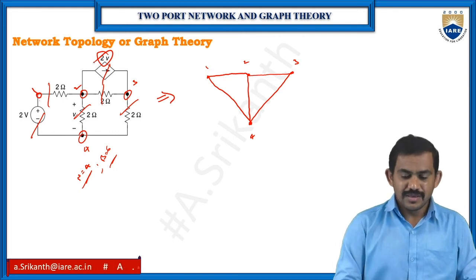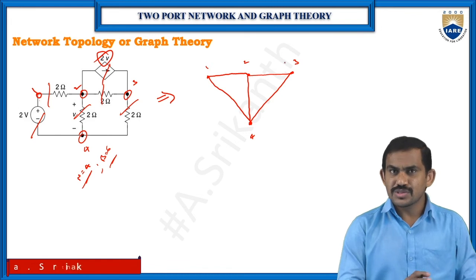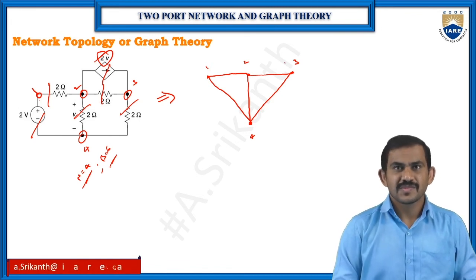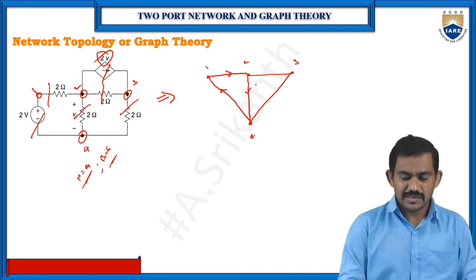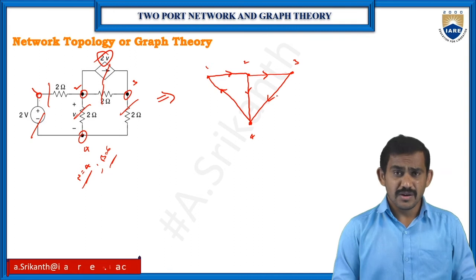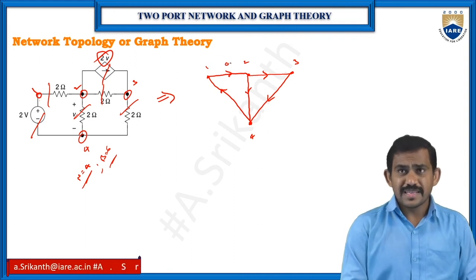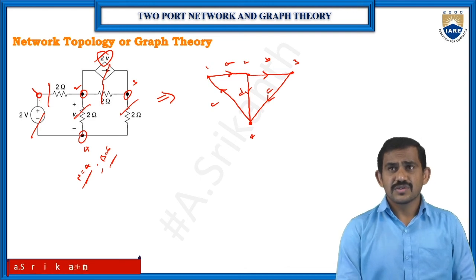It is a current source, depending upon a voltage. For a current source, we need to replace it with its internal resistance, so it is an open circuit. No need to draw the value. Give the directions, any direction. I want to use the source direction, so this is my direction. Now give the names for these branches A, B, C, D, and E.